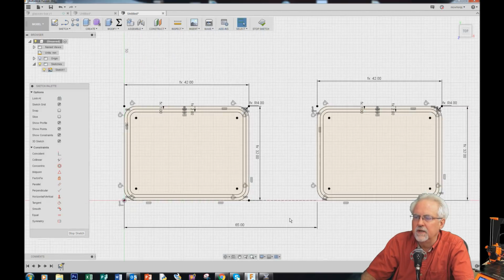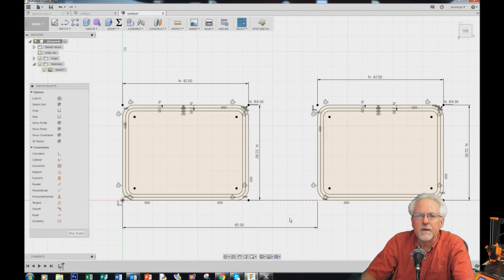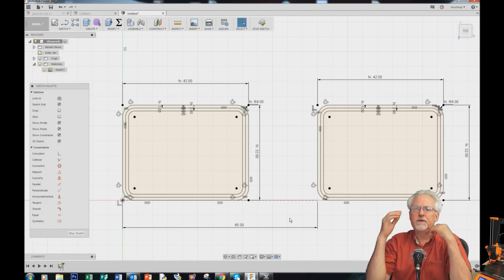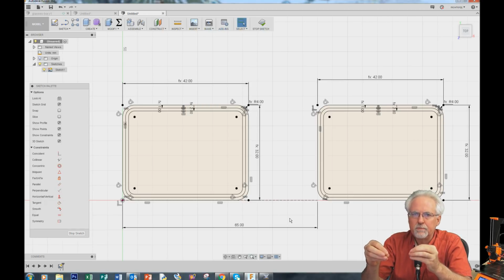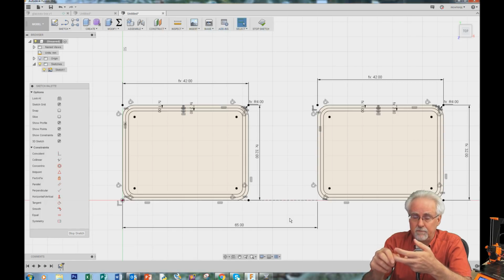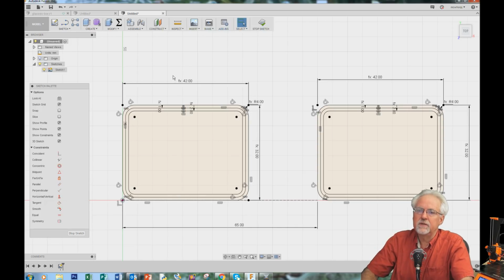These things look good. Okay, we are ready to what? We're ready to extrude, but at this point things are fun, things are easy. Why? You win or lose the battle of Fusion 360 in the sketch domain. What have we done? We've been mindful of dimension, position, constraints, and parameters. So we have defined a model that should always work. So let's do the fun part now.